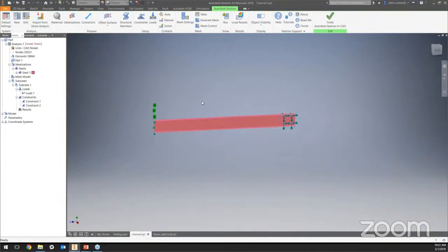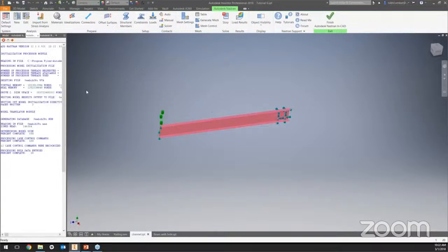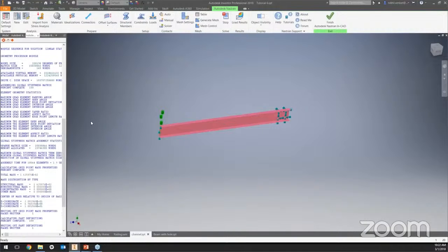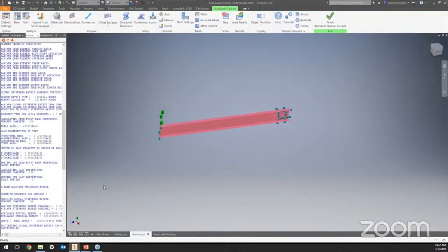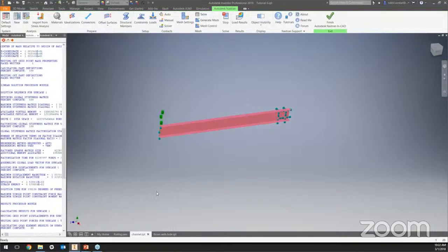We have all of our information in, so we should be good to run. And just keep note too that I know it seems pretty self-explanatory, but the more elements you have, the smaller you make those elements, the longer it's going to take to calculate this. So you could get infinitesimally small, but your computer might not be a huge fan of that.